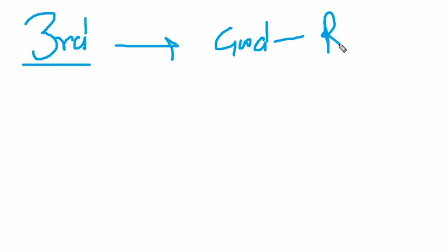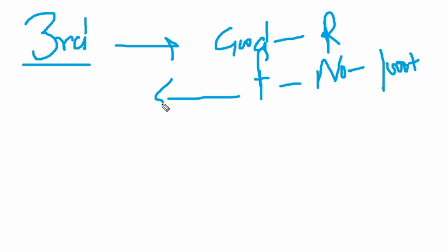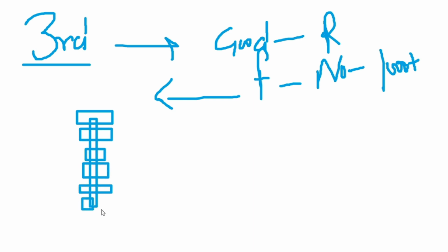In the third scenario, you get a good diode value on the connector on reverse bias. When you check on forward bias, there is no value or 1000 plus. That means this anode line is completely okay. Now after this, your first step is complete. Your display connector side diode value is okay.